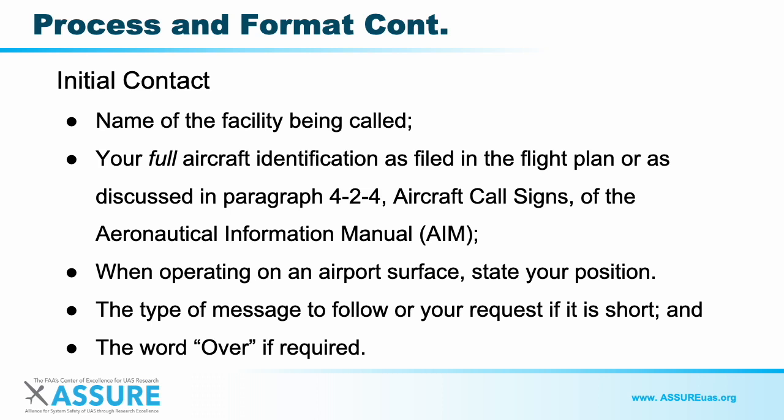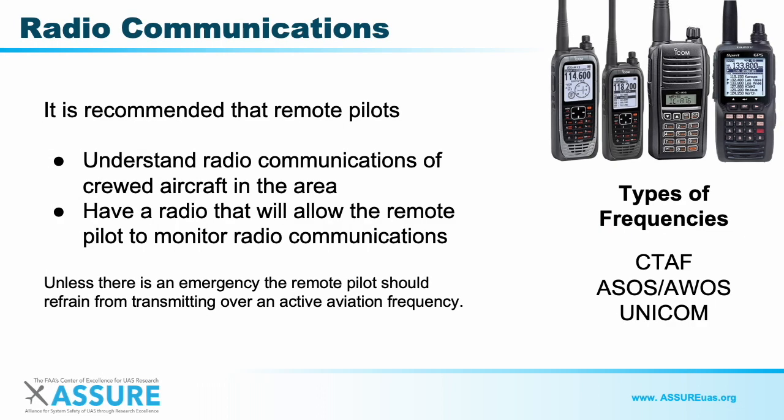When operating on an airport surface, state your position. You can include a brief statement to indicate the type of message to follow or your request if it is short, and use the word over if required. It is recommended that remote pilots understand radio communications of crewed aircraft in their flight area. Things like knowing the local frequencies of nearby airspace and airports beforehand can help in the event of an encounter with another aircraft. Of course, that won't do you much good without a means to communicate.